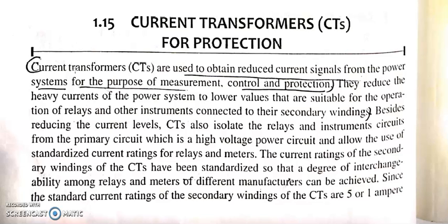Okay, for a few seconds, not for an hour or something. For a few seconds it will withstand even when the current reaches more than 50 times the designed, rated value. So this is the measure of current transformer performance and its ability to accurately produce current on the secondary side.